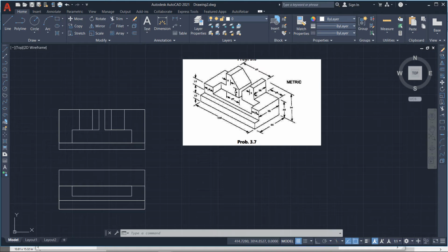Where I will draw the wedge, I will go 28 millimeter from the right side. From this point, right 28 millimeter, that is the point I got. I have already drawn the full height, so I will just press shift. So this is the height of this wedge.